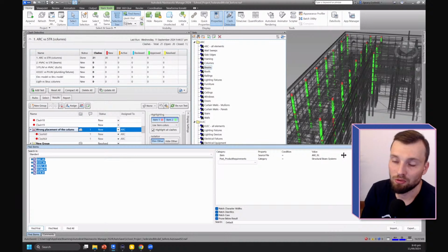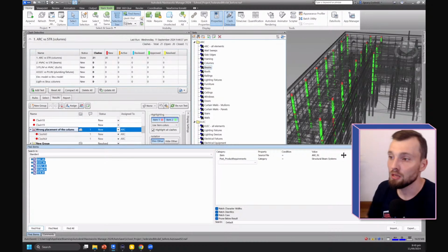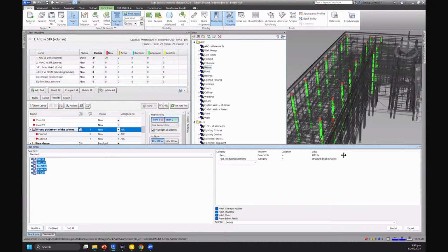Most probably when you are working with Navisworks and Revit files, all Revit files will group certain information in a certain property set, like element category. Then there will be walls, doors, and so on. So search sets can be used on different projects if this hierarchy of properties holds.